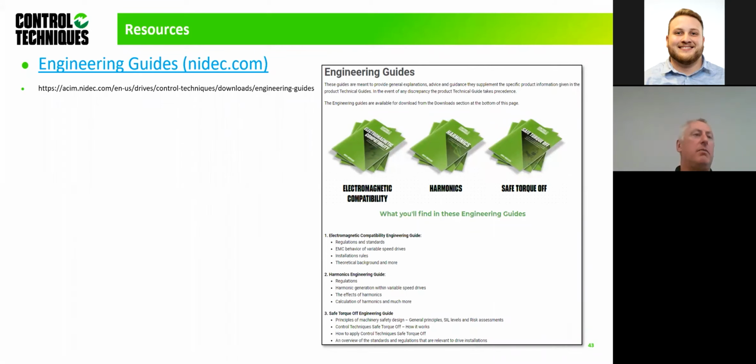Okay, so again, tweak the system. Someone's using my word from yesterday. But yeah, tweak the system. There's a couple of ways. If you can get to the system and it's existing, you can measure the voltage distortion, what's already on there, or get the impedance of the supply. And from that, you can make the relevant calculations for the generator. The easiest solution would probably be, can I upsize the generator, or can I put an input filter without having a large impact on the existing VFD?